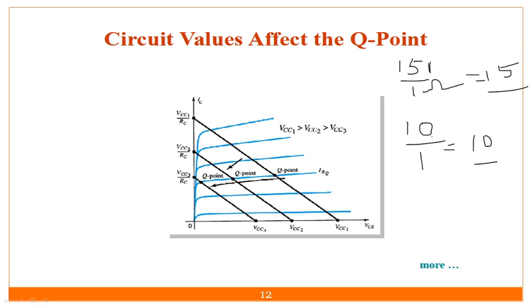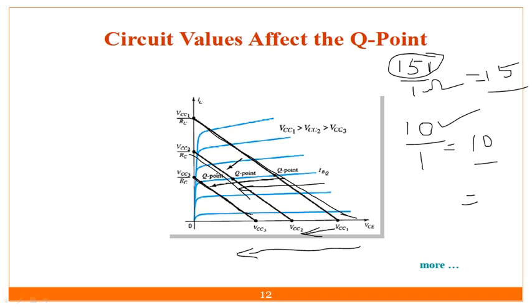Again, if I am decreasing the voltage, this point will decrease, and the line will shift from this end to this end. So the line totally depends upon VCC in the first case. And if I am talking about the Q point, it will again shift to this side, because the Q point is on this line only. The Q is nothing but the quiescent point. We will discuss this later. In this case, VCC1 is greater than VCC2 and VCC3.